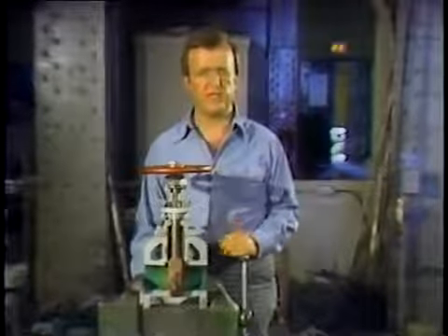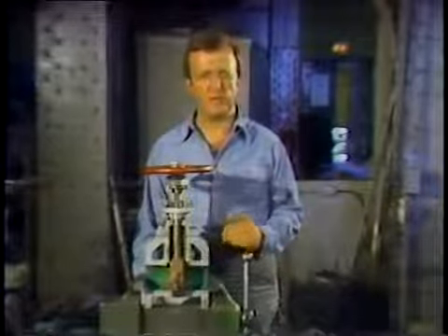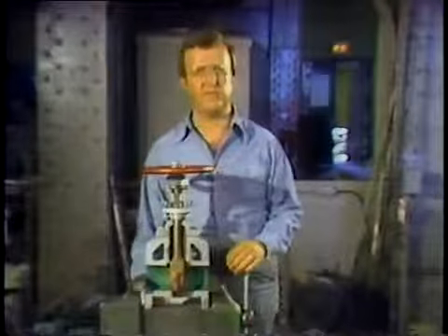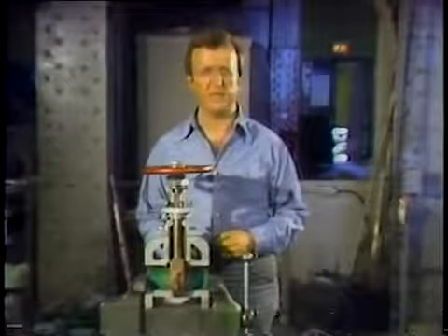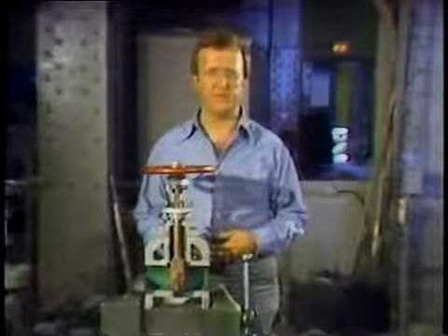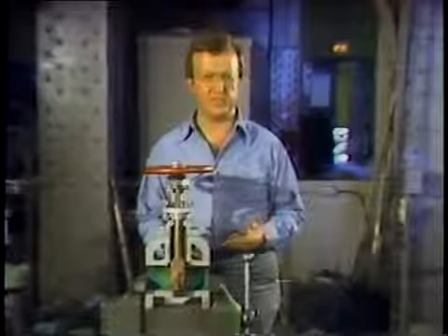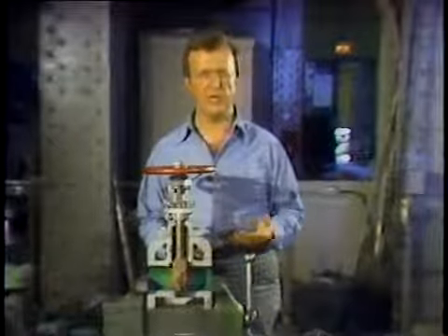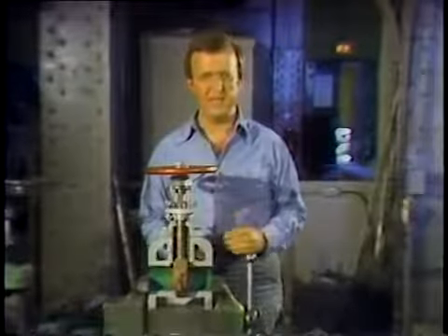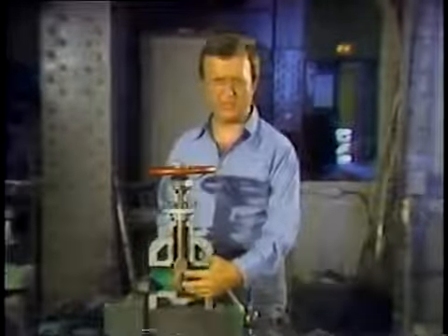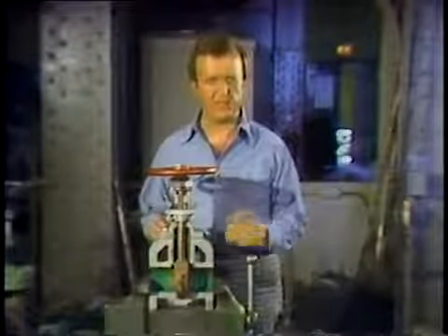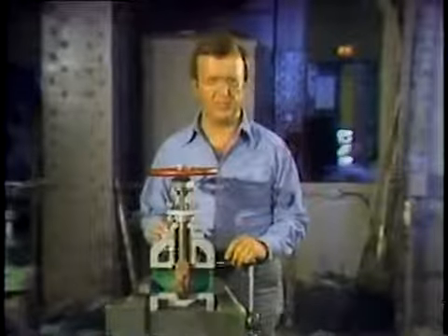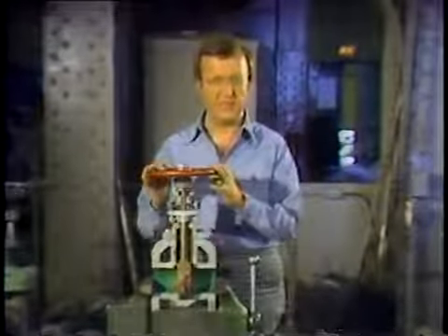The most common classification is by the shape or arrangement of the disc. Other ways to classify valves are by their function, the conditions under which they operate, such as temperature and pressure variations, and the way they attach to systems, such as by flanging, welding, or threading. Since disc arrangement or shape is the most common way to classify valves, let's take a brief look at some typical disc arrangements. This is a gate valve.